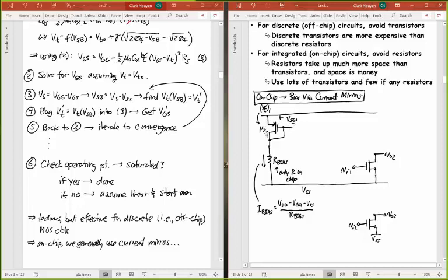So that's when I'm making this, and you'll see that's behaving like a diode. Now I've generated a voltage here. And the voltage right here gives me the exact voltage I need to generate this current. And so if I go back over here to complete this amplifier, and I give this amplifier, instead of a resistive load, a load that is a transistor, which I'll call M2, which has exactly the same W over L as the transistor on the left, and I then attach this to that gate, this is now going to give me exactly the same current.